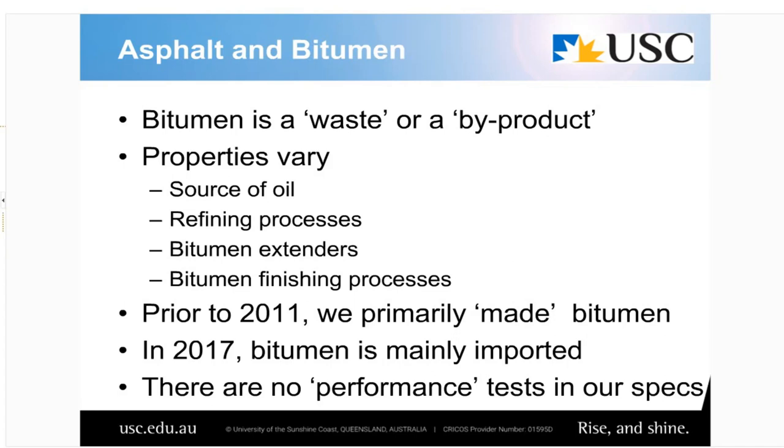The other thing lime is very good at is it promotes moisture resistance. It's primarily in there to stop asphalt stripping, which is water damage that gets in between the aggregate particle and the bitumen film and separates them. There are a number of airports that have had this issue recently.